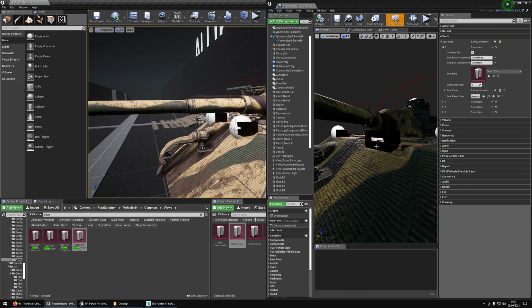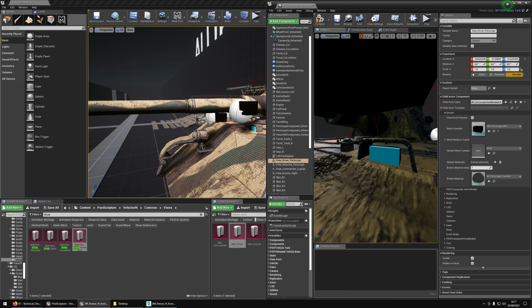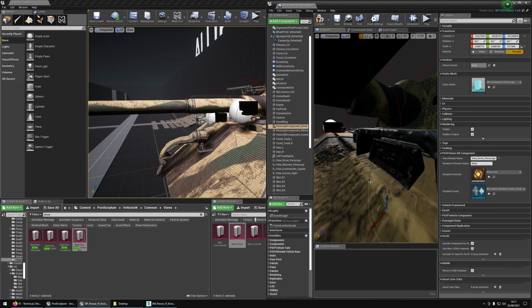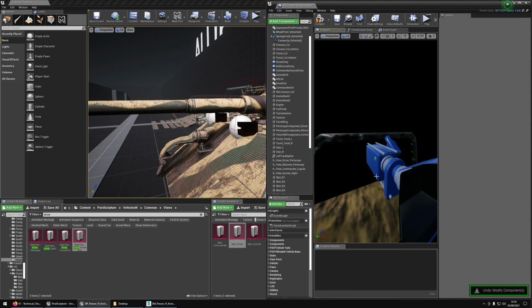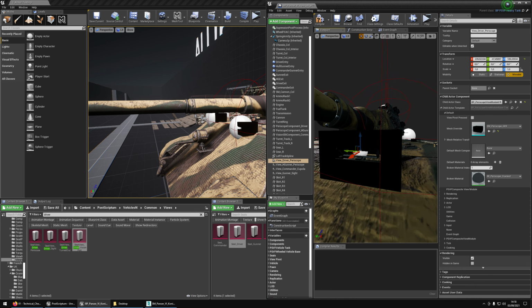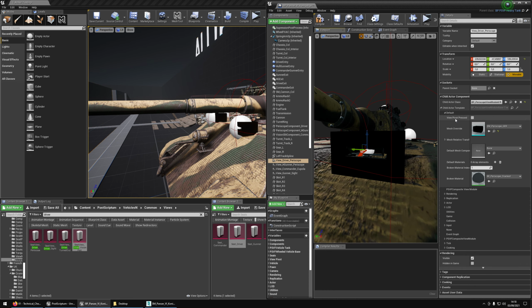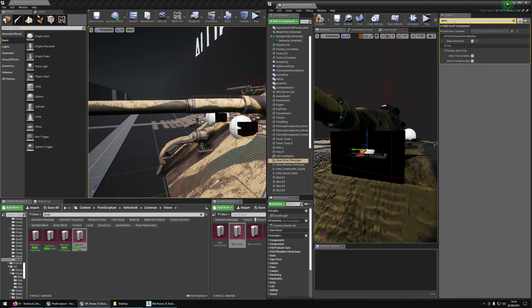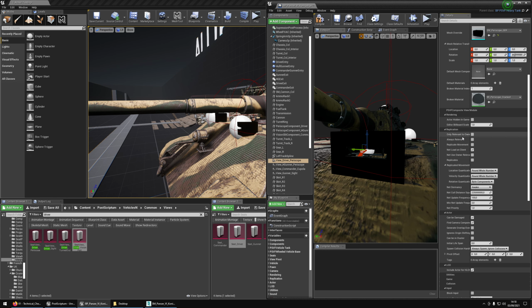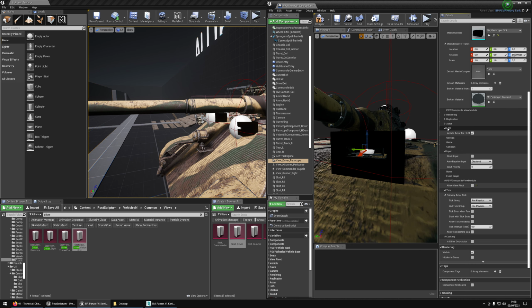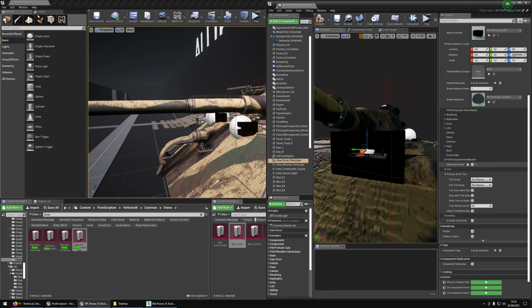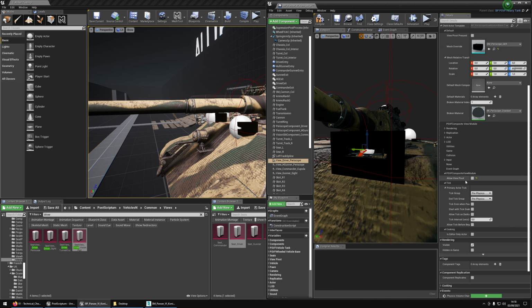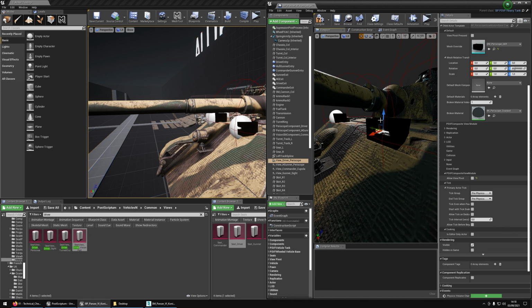First thing, is it a fixed periscope? How do I know that? I mean, this thing is not going to be able to rotate. If I look at, that is just a static periscope. So I would go here, and there should be here an option telling me allow to, I think that moved. Yes, oh, it's in composite view module. Okay, that's changed. Wasn't there yesterday. Composite view module. Oh, it's here now. Okay. It used to be right under the material. Now it's here. So if I click this guy, then when I press Control, I can look around rotating my periscope. And if I untick it, then it's a static periscope, which is what it is in this case.